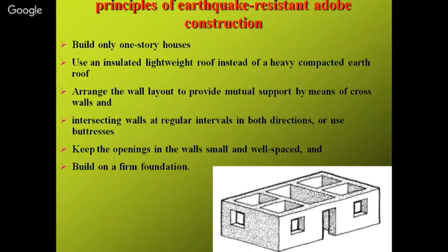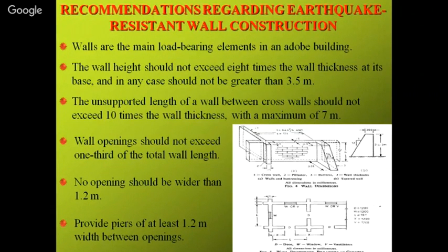Keep the openings in the walls as small as possible, because whenever you have big openings in your walls, if the earthquake force comes, when inertia force acts on the wall, in case of any action, in plane or out of plane, very little surface area of the wall is available to resist that force, so that wall will fall. So you need to have very few openings in the walls.